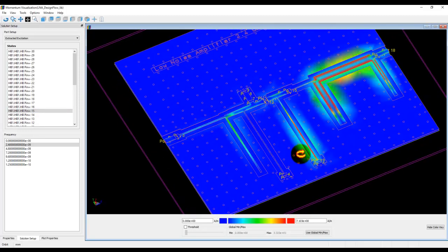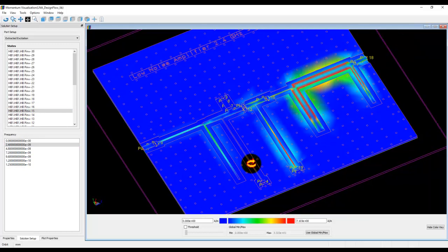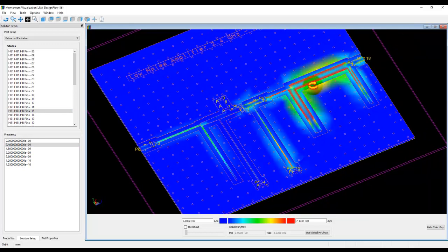Now, this is also very useful in case, at a certain power level or at a certain frequency, you have unwanted resonance, you can quickly capture it. Let's say my desired direction of the current propagation is that it should reach the output port. But if I have some accidental short circuit here, due to lambda by 4 open or whatever, unintentional, I will see the entire current getting sucked up here and virtually there is nothing going out.